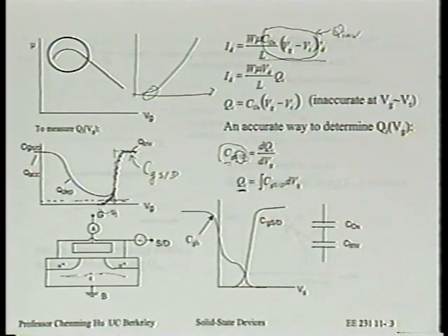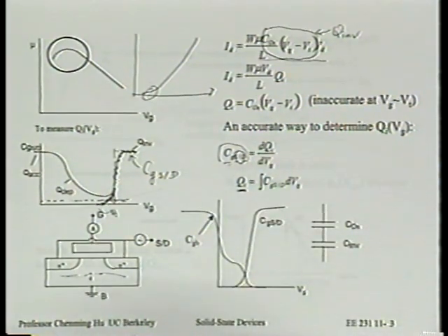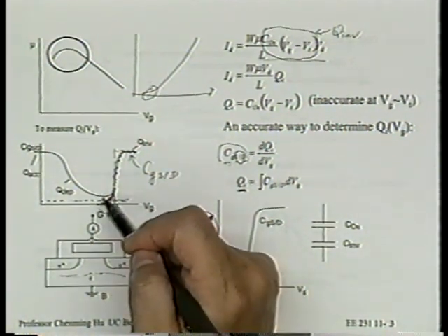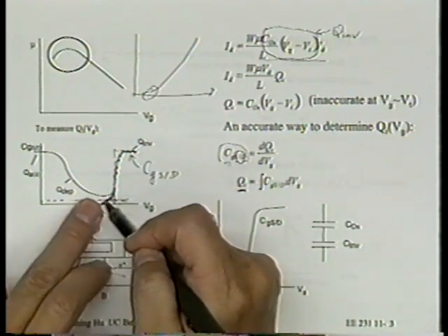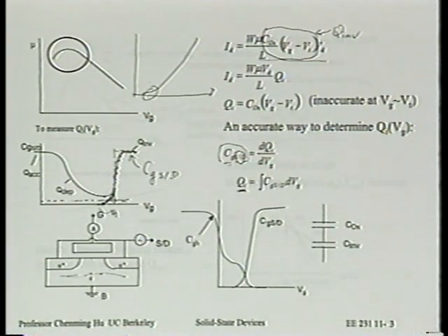Is that right? All right. So this automatically gives us a reference for where you cut off. You see? If you didn't have this effect, you would actually be in trouble, because very often, for example, this is a big trouble: how do we know this is the real minimum capacitance corresponding to the depletion region thickness? How do we know there's not a probe stray capacitance? What we sometimes do is lift the probe so that it doesn't touch the contact. But does that mean all the capacitance goes away? Doesn't the probe still have some capacitance left?